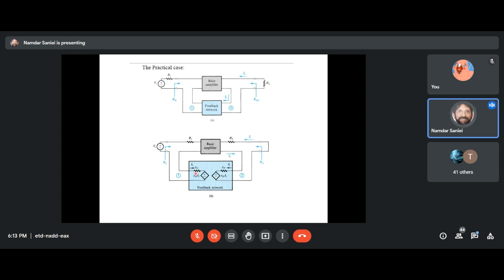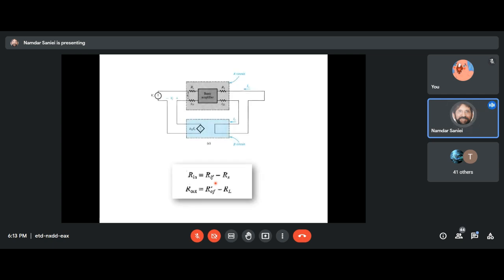So now we had to take these resistances out to the amplifier, and we would get rid of the source, this source here, due to the unilaterality of the feedback network. And we would only have one source and a short circuit in the feedback, like this. This would be the ideal situation.